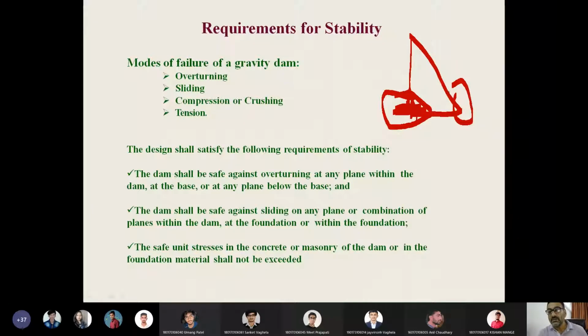So when we do calculation of resultant forces because of the stresses getting generated in the dam body, the tension is not directly the cause of failure, but the tension crack which generates onto the heel side leads to crushing of the toe, or the resultant going out of it, and the whole body of the dam will get tilted or overturned. So that is this type of failure.